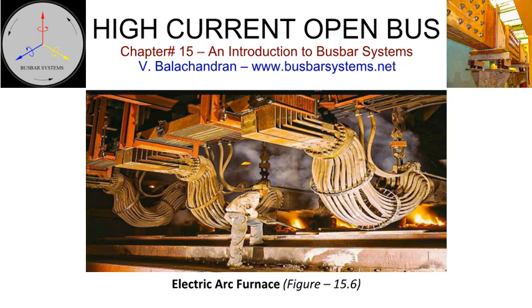A typical mid-sized furnace may have a transformer rated for 60 MVA with line current over 44 kA and a voltage varying between 400 volts to 900 volts. Currents of this magnitude can generate large electrodynamic forces between the cables. It can heat any metallic objects in the vicinity due to eddy current losses and hysteresis losses. The contribution of heat generated by the furnace to the ambient is so high that induced losses have only a marginal contribution.